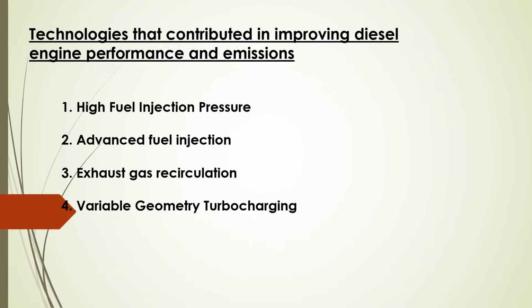Good day, Doctor. Today I want to present about the technologies that contributed in improving diesel engines' performance and emissions. First and foremost, the most dominant technology is the high fuel injection pressure, followed by advanced fuel injection, and the third one is the exhaust gas recirculation and variable geometry turbocharging.